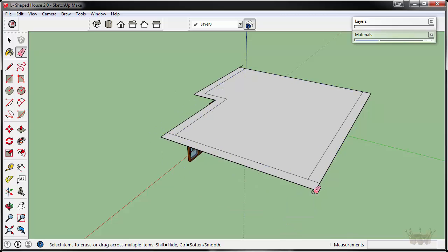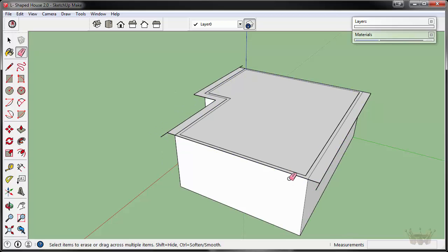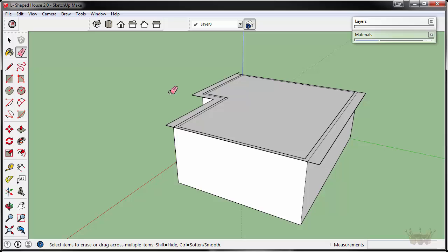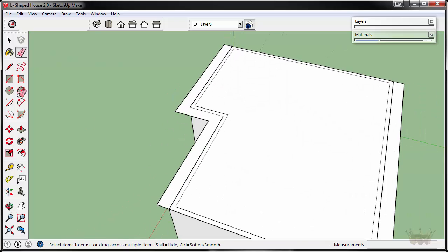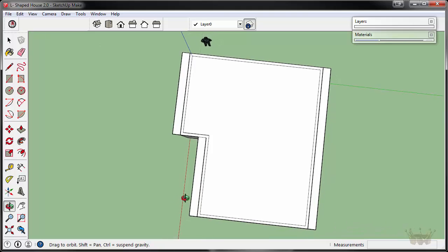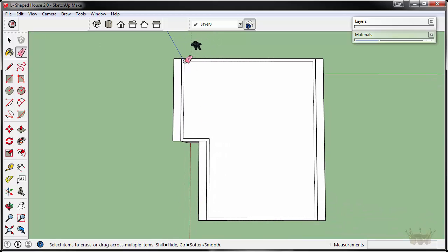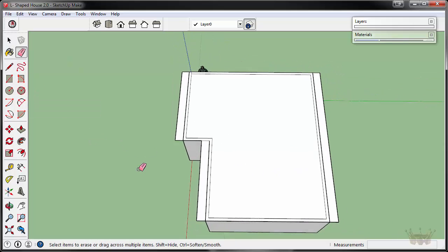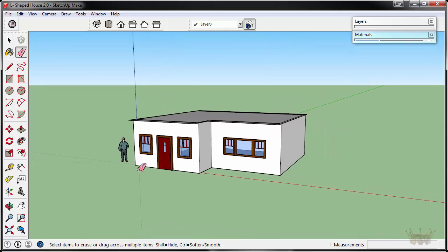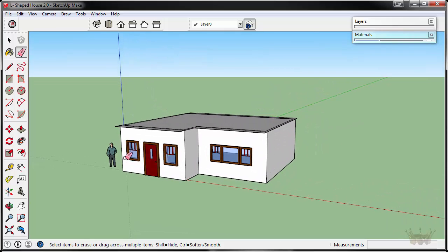Careful, if you accidentally delete the wall grouping like that, press delete or undo. And the final one we're going to take out, missed that one, is this line here and this line here. Now double check carefully that your roof looks like this. You should have an overhang 1, 2, 3 separate spots. If you do not, Control Z back and figure out where you went wrong. From here, we can now begin to build the roof of our house.